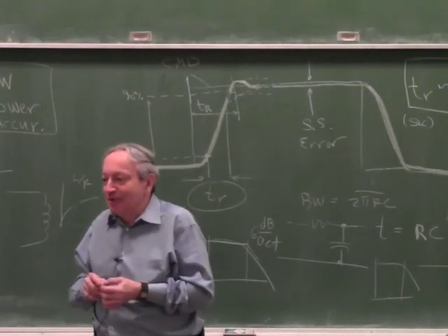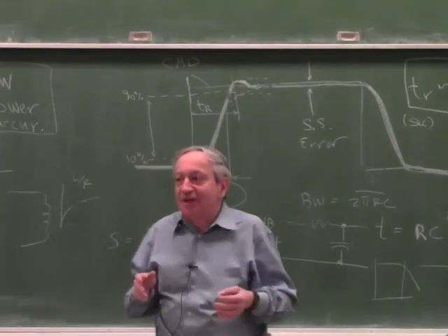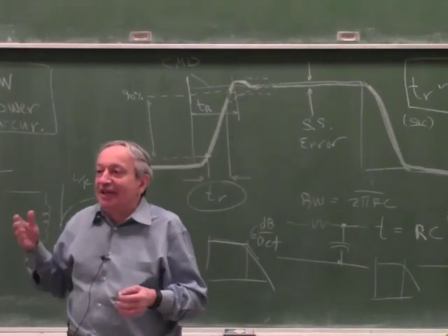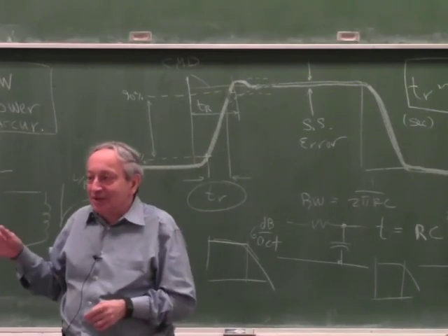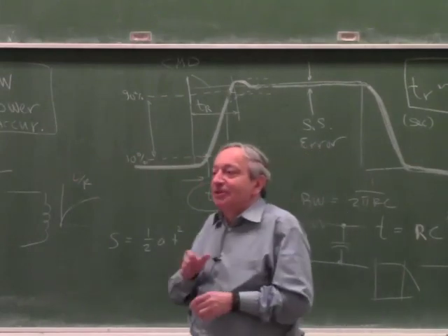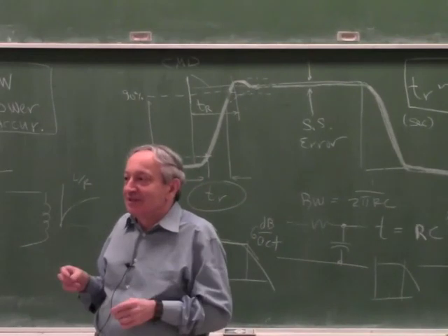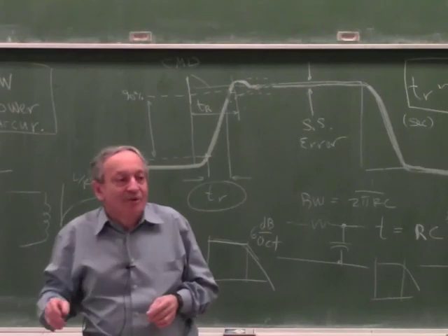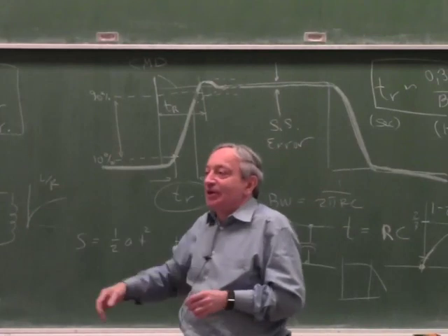How come only you remembered? So there's two reasons. One reason, most servo systems are digital today. You're going into an A to D converter. If you don't put a filter, there will be aliasing. And I don't want to start this whole lecture again on what aliasing is. But okay? But there's a second reason too. So if it's a digital system, it has to have a filter. Otherwise, some frequencies will get created which didn't exist. And these frequencies can be very low frequencies that the actuator will respond to. That's called aliasing. But there's a second reason why you can't just allow unrestricted bandwidths to get into the amplifier.